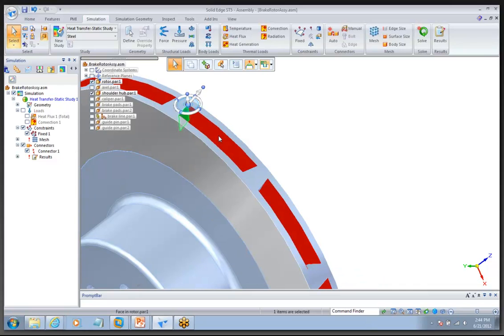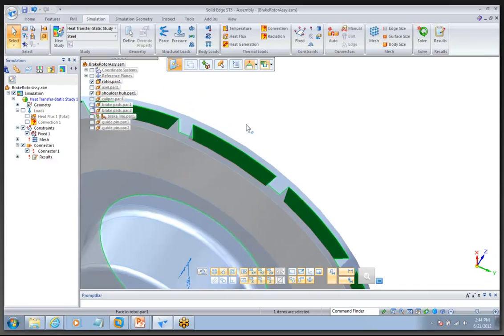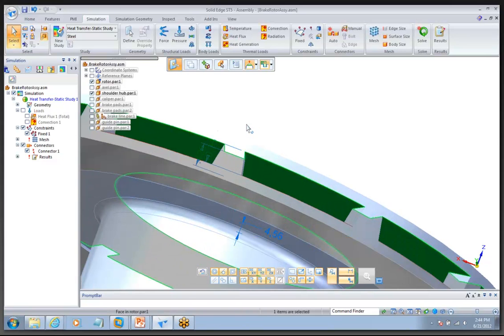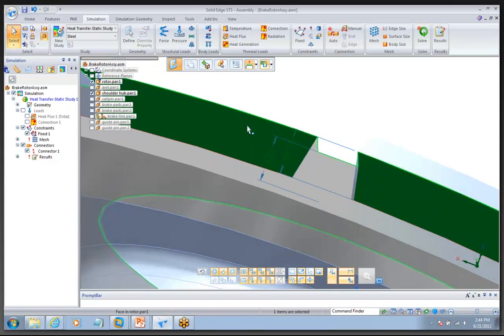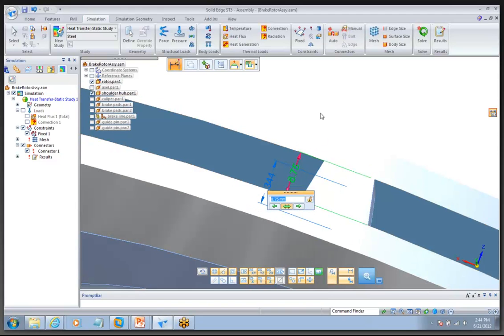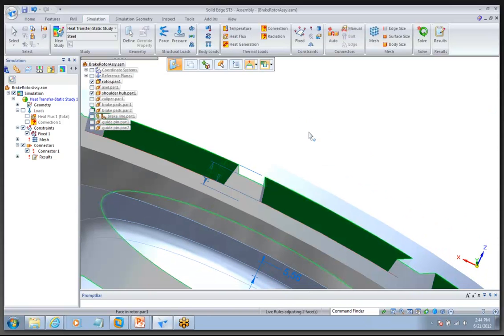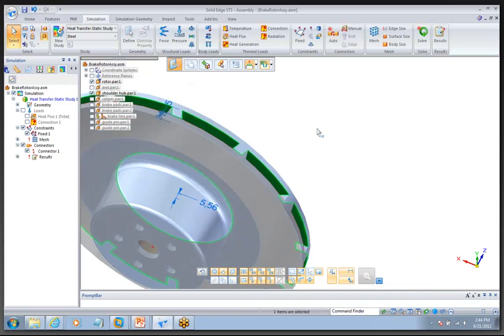And then the last thing I want to do, I'm going to zoom around here to find my dimension. There it is. And new with ST5, I want to make this thicker. New with ST5, we can move both sides at the same time, selecting this middle button here, and you'll see how that keeps things symmetric. So I made that a little bit thicker. And really that's all I wanted to do with my changes.